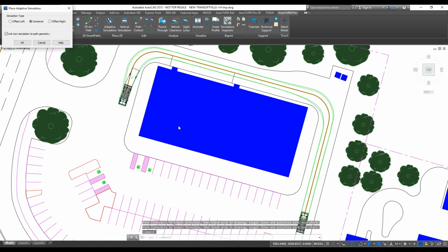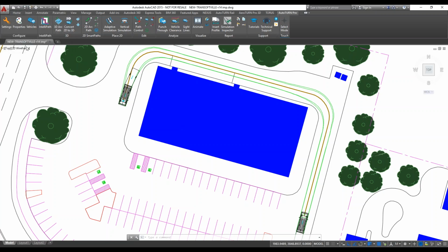We can see it follows that centerline geometry, but the off-tracking is different. However, because this is a two-part vehicle, likely the driver will oversteer to make that turn. In this case, we're assuming they will all follow the same path. So another key difference, we just stick to the path.